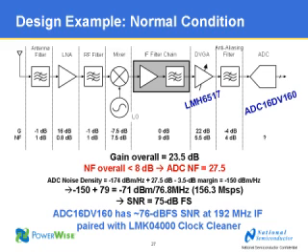So we talked about the ADC noise figure of 27.5 dB. We did mention the low noise figure of the 6517 comes into play and becomes very important here. In the case of overall gain in the normal condition, we want to just basically maximize the gain of the DVGA and get the maximum gain through the whole chain. Now, using the ADC noise figure of 27.5 dB with the 3.5 dB margin that we add on top of it, we get about minus 150 dBm per hertz, the noise density of the ADC. Now, that translates into 75 dBFS SNR at the sample rate that we discussed, the 153.6.